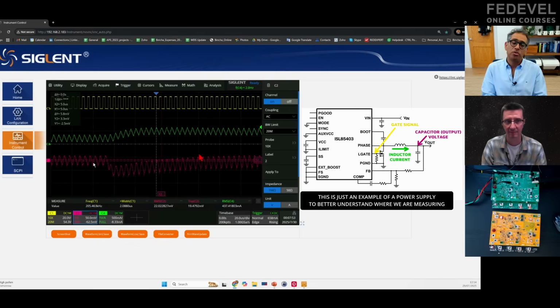And if you are using electrolytic, there is a different calculation for the ripple. And then on top of that, there is the voltage undershoot calculation, right? So you have two different requirements for calculating the size of your capacitor, three if you consider that sometimes you have electrolytics and sometimes you have ceramics.